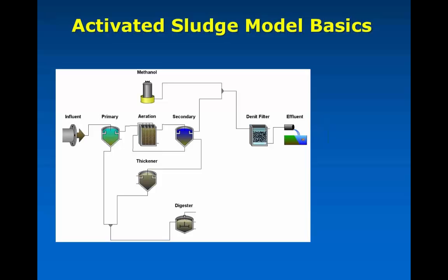By that I mean all of the state variables that are going to be solved for: the concentrations of all the forms of COD and nitrogen and phosphorus, the pH, and all the calculations for gas transfer and so on. That makes for quite a long list of variables that we're calculating and solving for when we run a typical activated sludge model like the one I'm showing here.